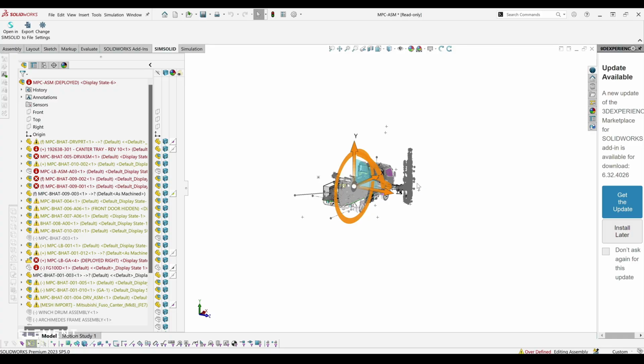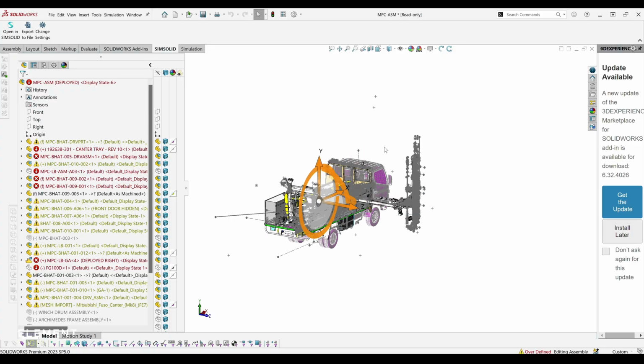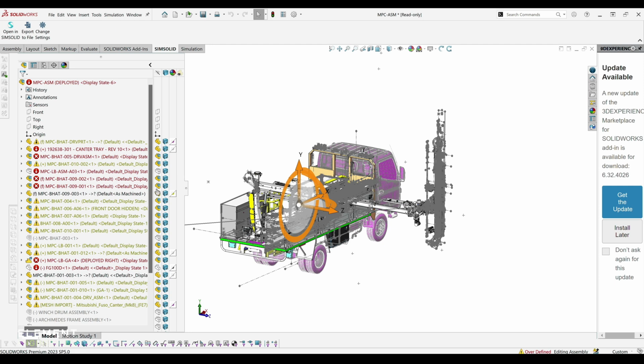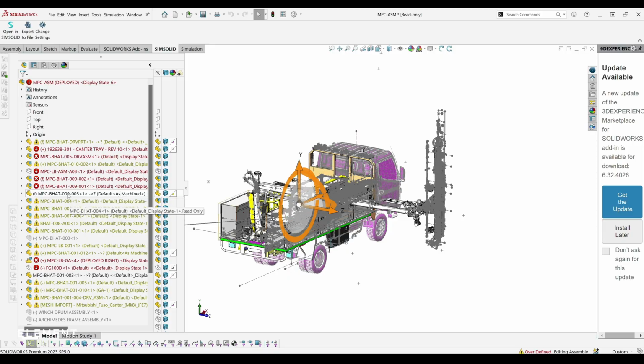Particularly if that client is going to use that as a manufacturer package, it may turn into a V2, V3 later down the track. That was the case with this model here. This is obviously a production grade model, and you can see the feature tree is pretty messy. This model's not crashed, but it's got some issues with mates and stuff, but it's okay. It's okay to be like that if we got the customer to where they needed to be. In this feature tree, even the way it's broken down, everything is named. We've got a part numbering scheme that we follow across all jobs in the business, unless a client has their own scheme that they want us to use, and then we would obviously adopt that.